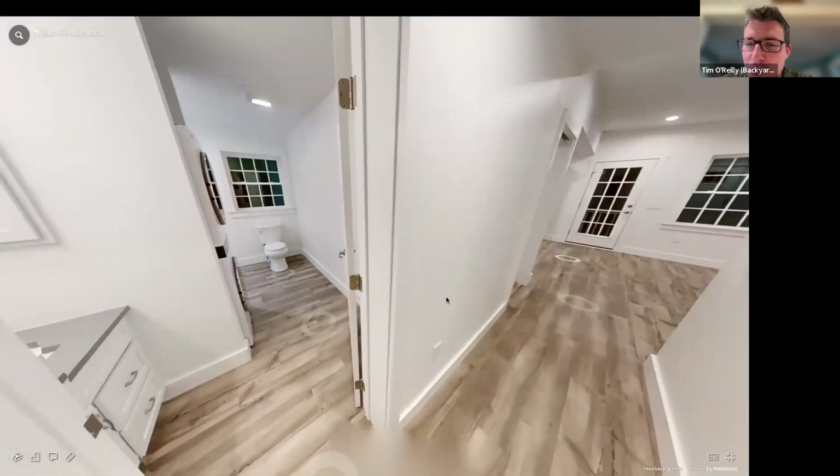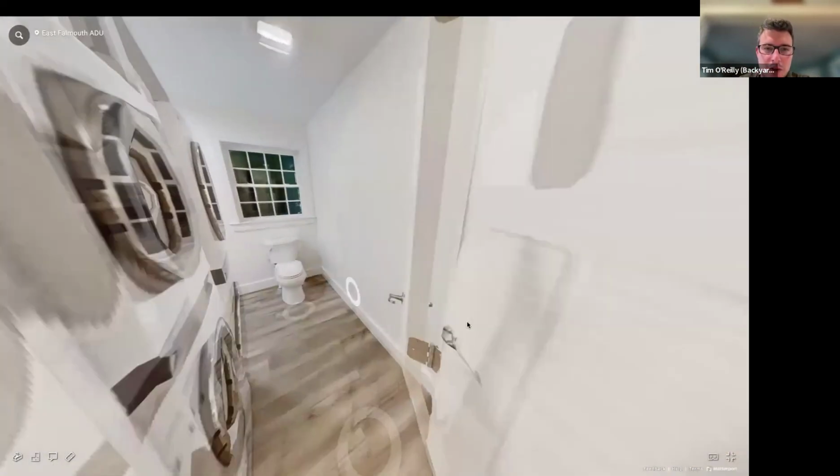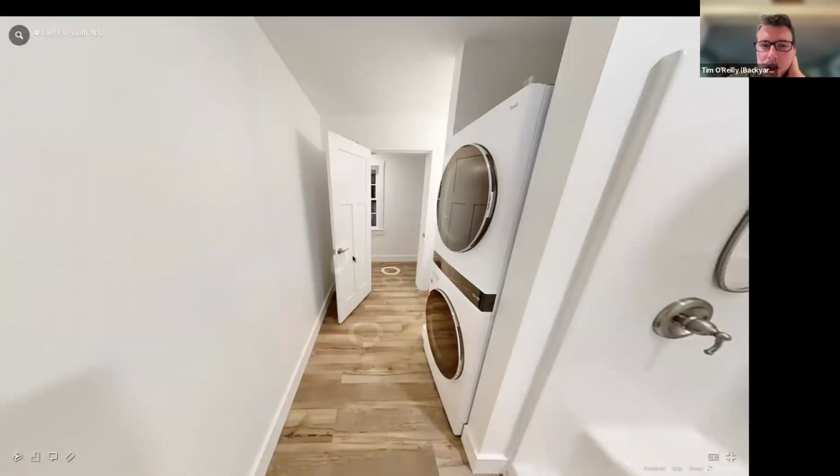The bathroom is the last thing I wanted to highlight. On the floor plan, we wanted to design, again, functionality now and accessibility long-term. So we actually ended up leaving and offsetting the door about 18 inches. That gives her the flexibility for most furniture storage, whether it's IKEA or somewhere else, to have some sort of organizer or shelves or system to fit snugly behind that door, where she can still navigate this space. If she ever needed the extra couple inches, she could remove that piece of furniture.